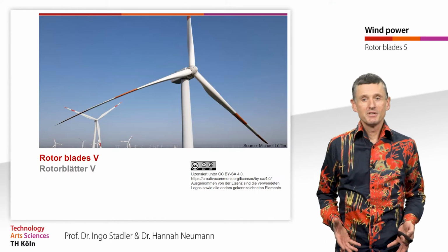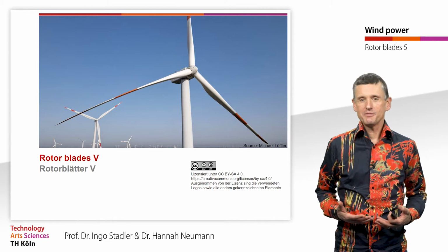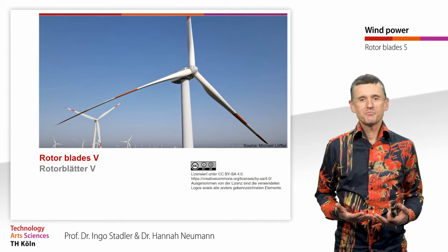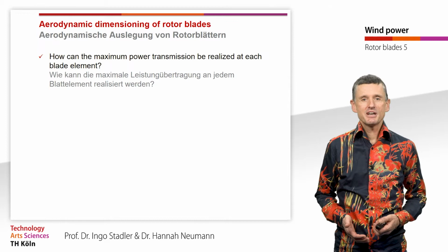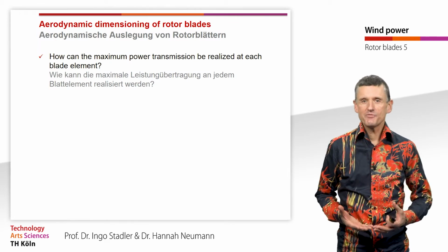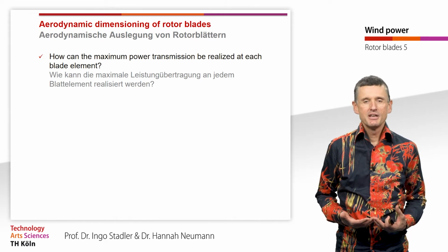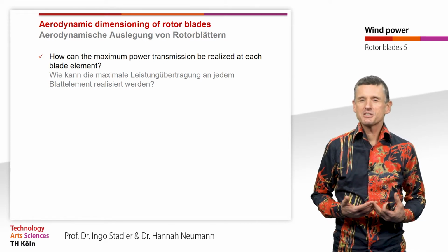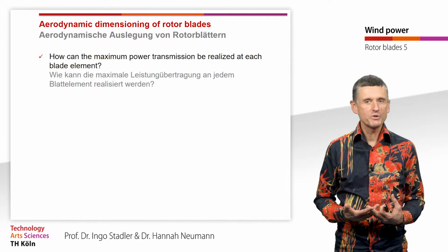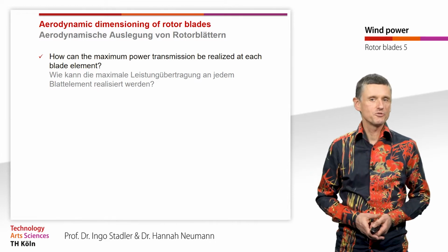Hello and welcome. In this video we will keep this perspective of the blade element theory, but this time we aim at a different thing. This time we are looking at the forces at the blade elements in order to transmit the maximum possible power from the wind to the movement of the rotor blades.